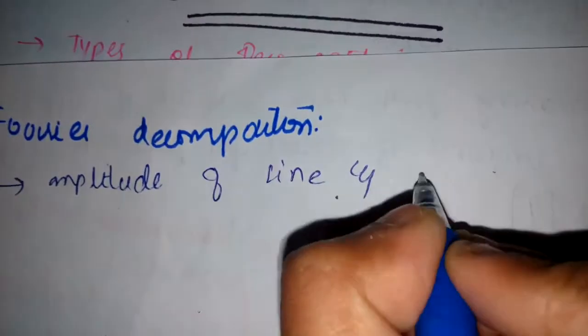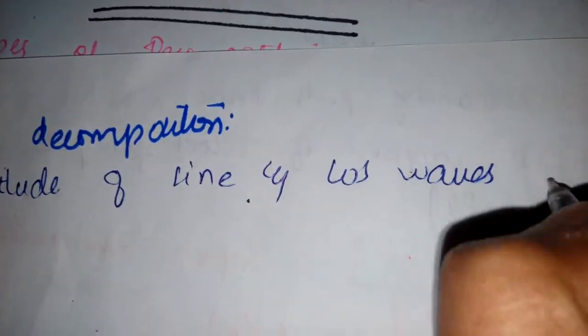The lowest frequency cosine wave makes 0 complete cycles over the n samples, and it is DC. The next cosine component follows, and this pattern holds for the remainder of the cosine waves as well as for the sine wave components. Since the frequency of each component is fixed, the only thing that changes for different signals being decomposed is the amplitude of each sine and cosine wave.